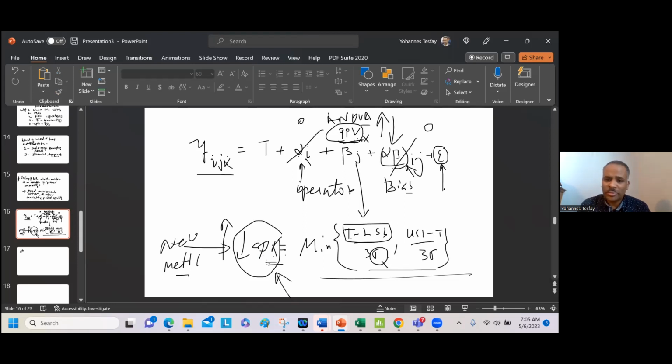No, the answer is: part to part variation is an indicator of CPK. If part to part variation is significant, then you're going to expect low CPK. If part to part variation is low, then you're going to expect large CPK. That's what it is. That's where they connect.